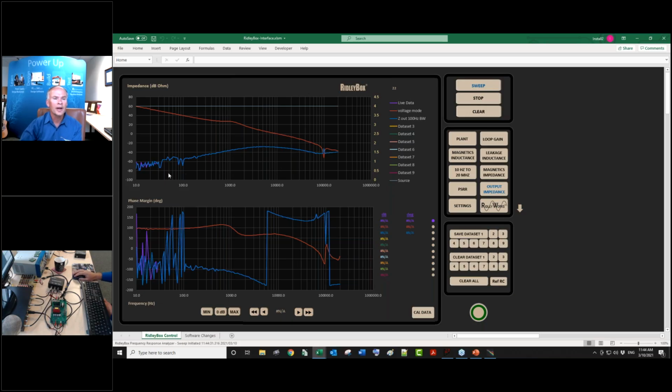And that cleans it up there. Oops, a bit of noise there. It's not happy about that. But, you know, what can we do? That's 1 milliohm, so we're down another 10 dB. So we're about 300 microohms multiplied by 50 milliamps. So the fact that it's measuring anything down here is pretty good. This is a tough signal to measure. So now you think, okay, we're going to try and use this for predicting loop gain, which I think somebody asked before. Well, the measurement's not very good here. This is just a tough measurement. But you see it's cleaned it up in this region here. Let's make that better. Okay.